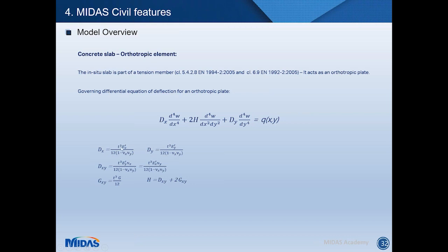These parameters are not of much use to civil engineers because we don't have the luxury of testing our big slabs on our bridges. But if you go to a book on numerical modeling for plates, you can find these equations which relate the inertias in the two directions of your slab for the steel part and the concrete part, and the elastic modulus for steel and concrete as found in the codes.